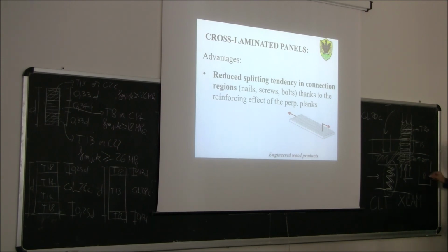If you remember that the fibers are oriented this way, a typical failure would be a shear failure between the hole and the end of the fiber, along this weak plane, remember the middle lamella between the fibers. So the typical shear failure would be a shear along those two surfaces here.